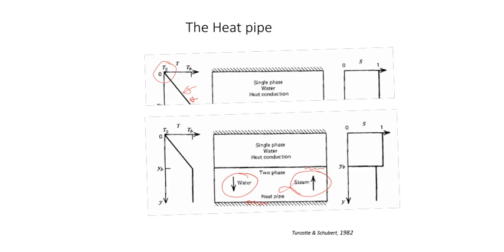There is therefore an exchange of latent heat, boiling here, condensation here, between the bottom and the top of the heat pipe. Because the latent heat is very high, the heat pipe is a very powerful heat exchanger. Note there is a mass conservation here in the heat pipe. So this is a conduction regime and the convection here in the two-phase layer.